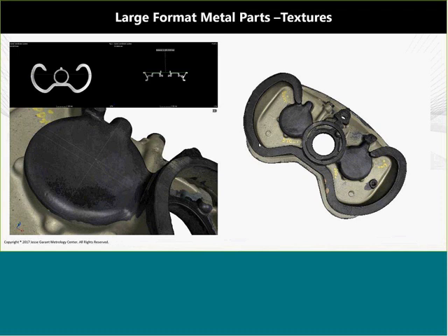Well, what that means is that in order for any measurement to be trusted, it needs to be correlated. Okay? And traditionally in the past, most CMM inspection has required scribe lines to make sure that everybody is taking the measurement at exactly the same location. So with the inclusion of textures, we're able to overlay that texture information on top of the CT scan, so we can match apples to apples. That way we know exactly where the part needs to be measured, and we can correlate that back.